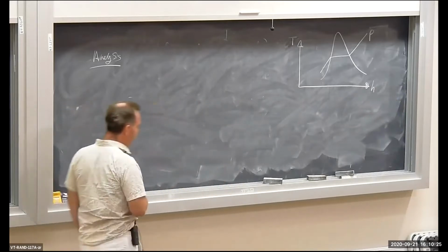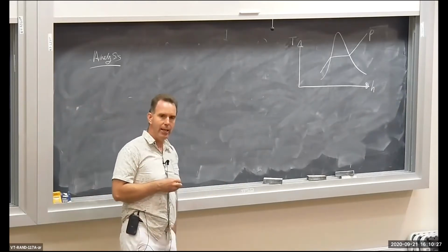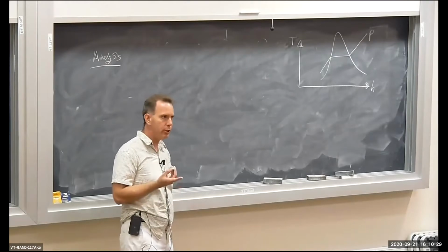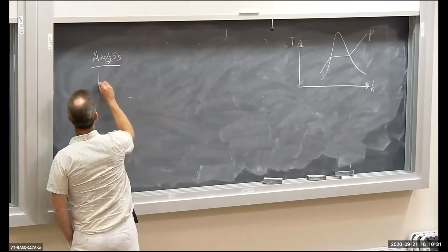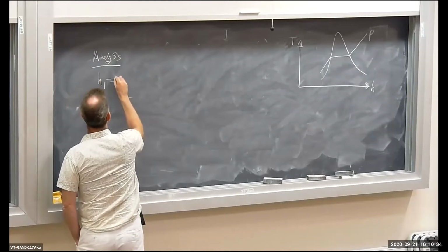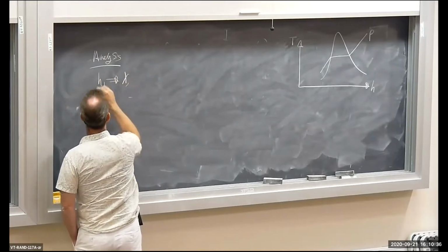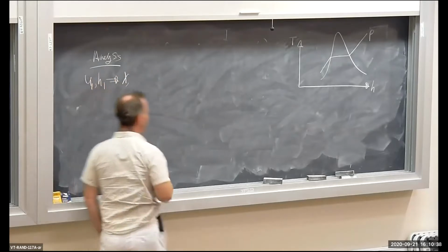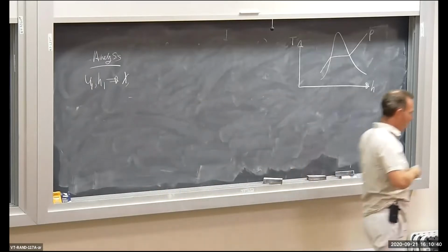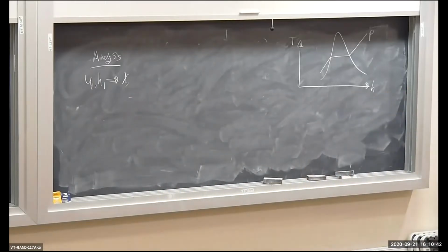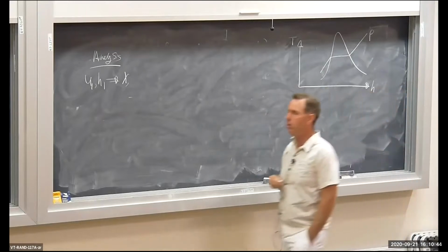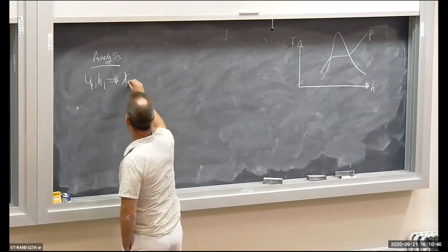Now, if I had an inlet enthalpy, H1, or an internal energy, I could get a quality at state 1. If I had a U1, a specific internal energy, or a specific enthalpy at the inlet, I could get the quality at state 1. Okay?